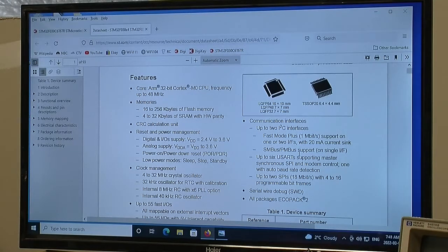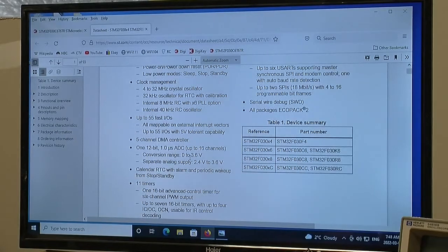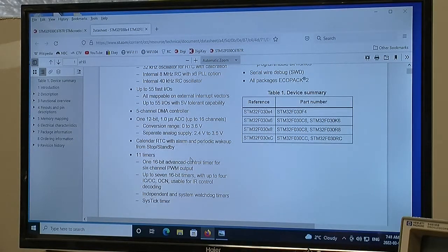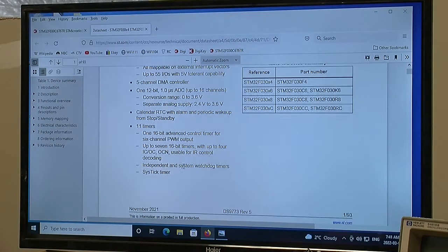That would be great to communicate with other devices on the circuit board, probably most notably the sensor in the bullseye of the donut. And somewhere else here I also saw there was a pulse width modulator output that might be used to control the heating voltage on the donut, so with a very efficient form of on-off type control to keep the temperature okay.